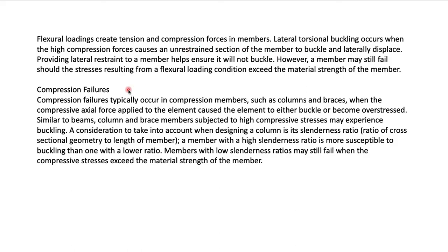And next one, compression failures. The third one is compression failure. Compression failure typically occurs in compression members such as columns and braces. Compressive axial force applied to the element causes the element to buckle or become overstressed. Similar to beams, columns and braces are subject to high compressive stresses and may experience buckling also.